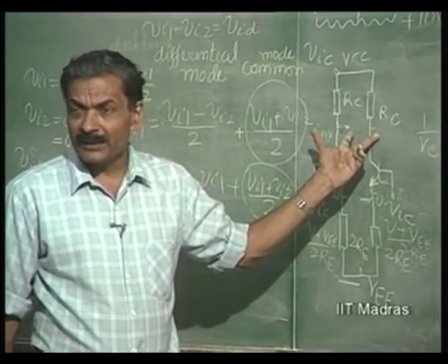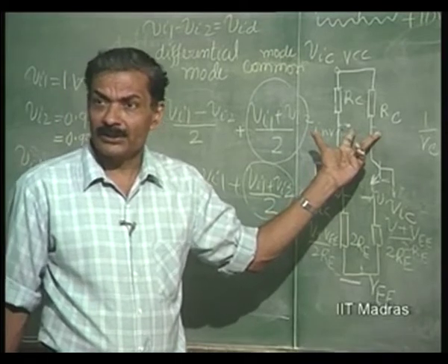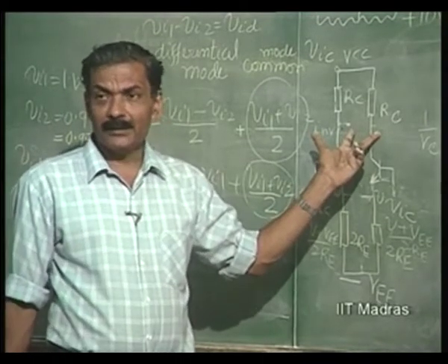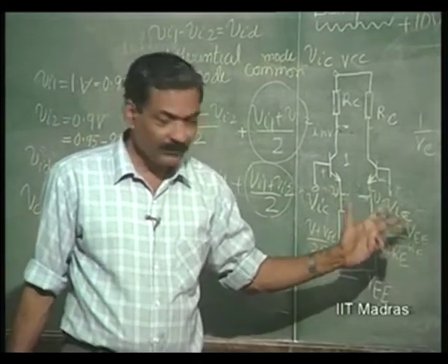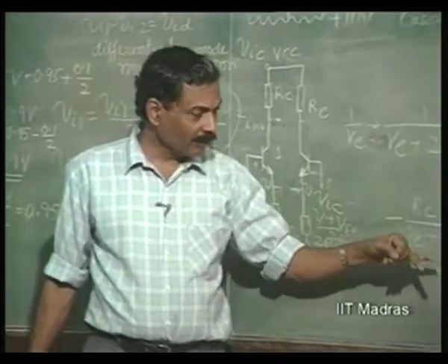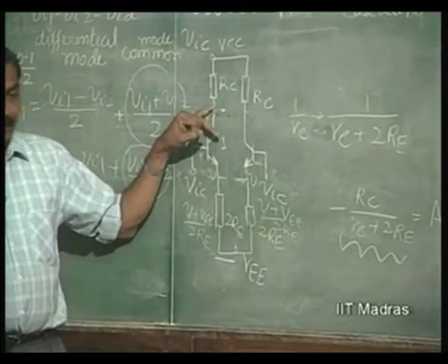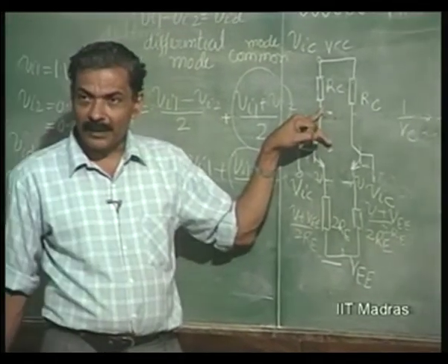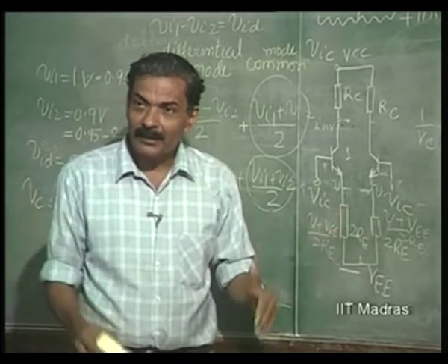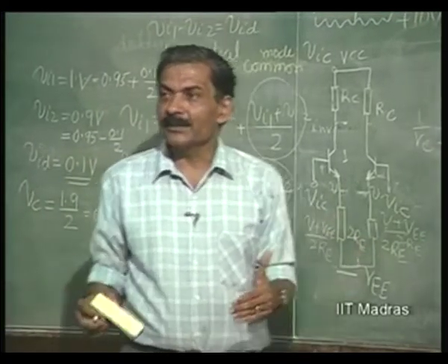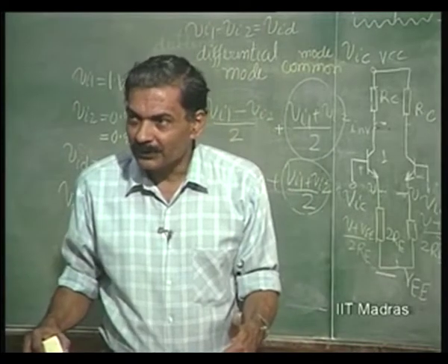Differential common mode gain in a symmetrical circuit is always 0, but in practice these may not be so identical. Therefore, we should compare the individual gains. These themselves must be made to go towards 0, and then if there is a mismatch, the differential output will still be closer to 0.